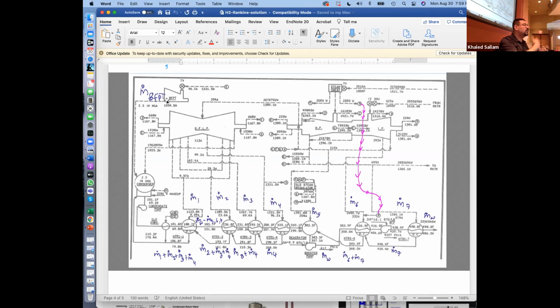to turn a pump. I mean, if it's just a pump, I need a shaft. I have steam. I can make my own work, but from the turbine to the pump, and I cut the middleman. What's the middleman? The generator and the electric motor, that they have efficiency. And when it comes to that pump that does the main work, I cannot afford to lose over generator and over. But the smaller ones, those can run with electric current. That's okay, especially that they are far away too, right?